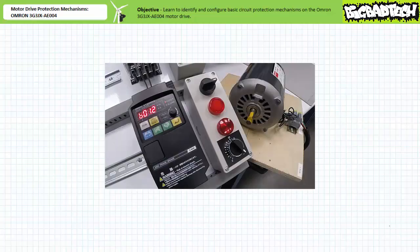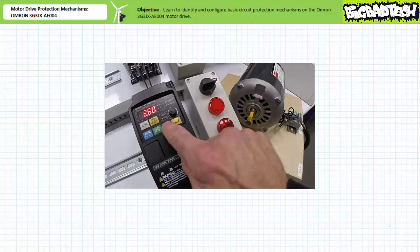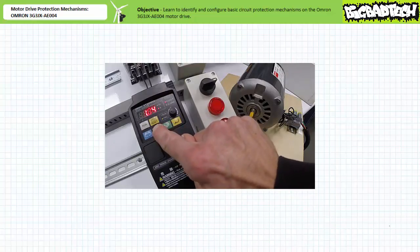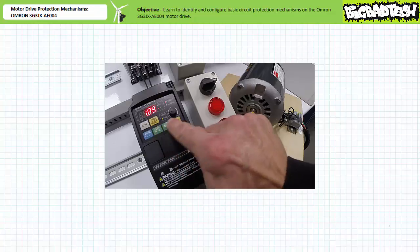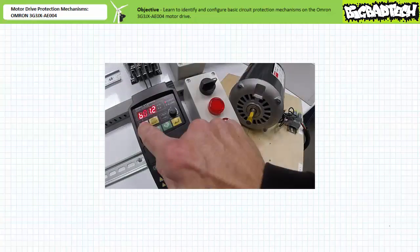Navigate to protection parameter B012, electronic thermal level. As anticipated, the default value is the rated current of 2.6 amps. Let's decrement this value to, let's say, 1.09 amps. This value is just below the steady state run value of 1.1 to 1.2-ish amps. Given this relationship, the drive should run, however, it will eventually overload. Let's see if this is the case.